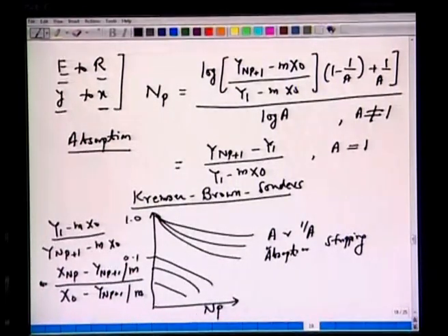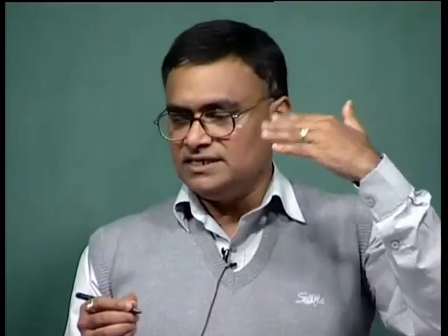All right, so this was a very special case where we assume that the equilibrium curve is a straight line. So in that case, one doesn't have to make a material balance for every stage, 10 stages, 20 stages. We can use these expressions directly. We have to be careful: the mass transfer is from which to which phase, extract to raffinate, E to R phase or R to E phase.